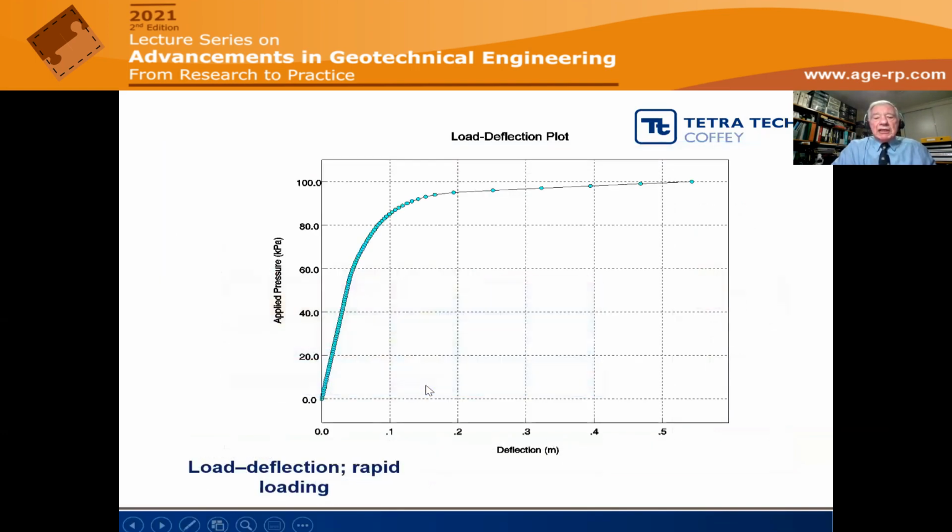And the interesting thing is that here is the load settlement behavior, that now we have a stiffer response, which is because the initial settlement, of course, is less than the total settlement. But you see that we get an ultimate load pressure, which is 100 kilopascals, which is almost a third of the bearing capacity long term.